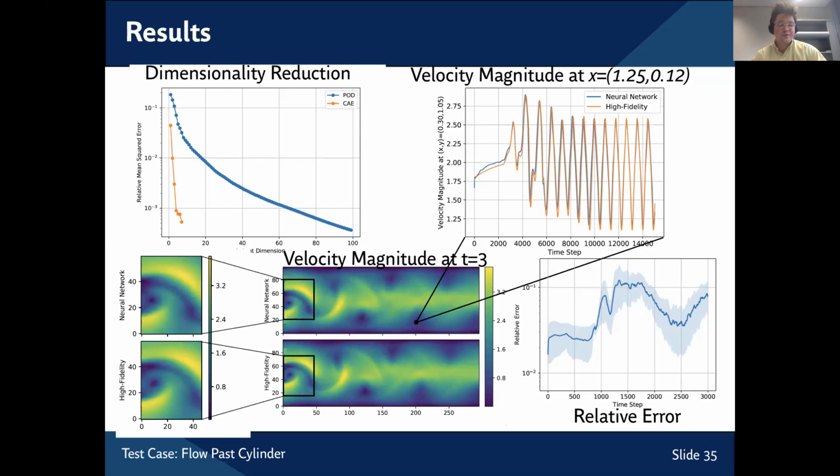when you project your high fidelity state onto your reduced space, then you get the parameter in front of a series of basis functions in proper orthogonal decomposition. So in this autoencoder framework, you don't have a linear combination of basis functions, but you have a non-linear encoding. So it's slightly more abstract, but at least to me, the easiest way of imagining it is seeing it as a generalization of proper orthogonal decomposition.